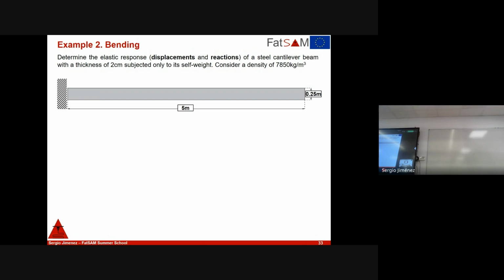No, you are in the finite element view. So you need first to switch to the geometry view, and once you are in the geometry view, you need to switch. Now by doing that, you are in the geometry, and now you can do it, but you need to get out from this environment. You can do that, but then finish with this, and I will sort something, because one of the processes maybe has not properly been created, and it may create some conflicts. So assign the corresponding boundary condition, and then we have it.